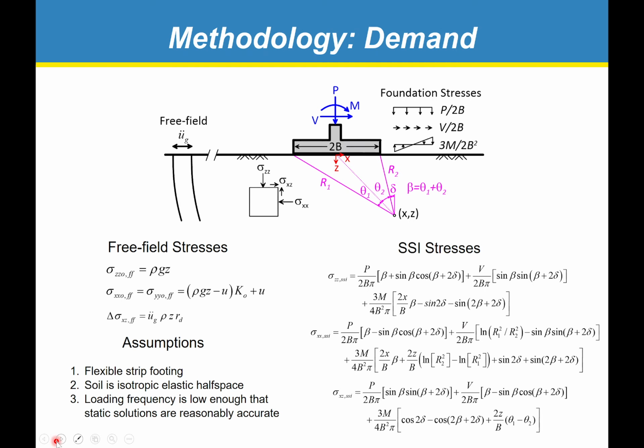So our methodology is going to focus on two aspects. One is demand, right? So we're going to assume vertically propagating shear waves in the free field, but then those combine with SSI-induced stresses from a shallow foundation. And what we'll do is limit ourselves to plane strain condition, although the concepts are general enough that you could substitute these for three-dimensional equations for the stress field beneath a loaded area.